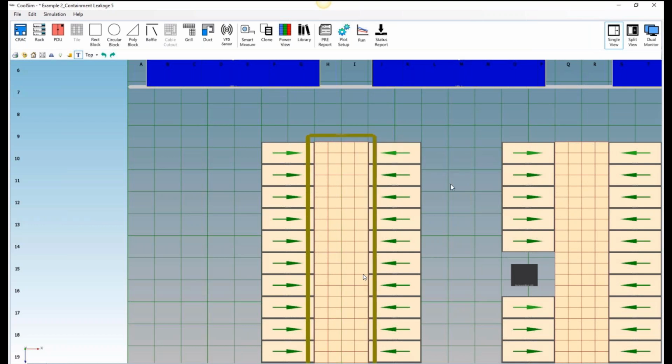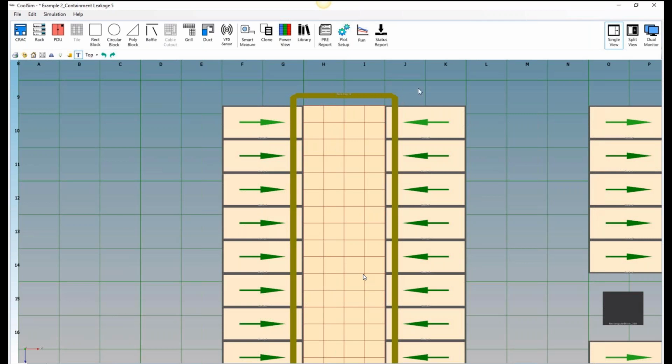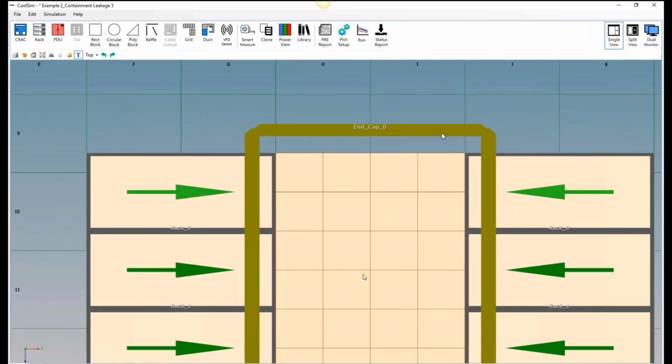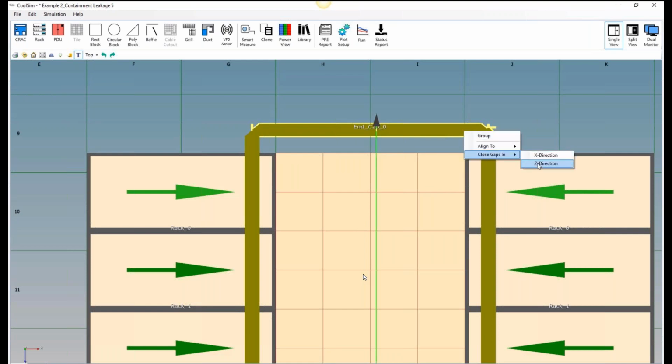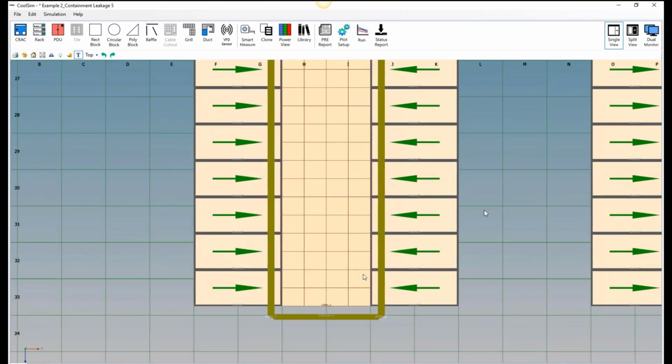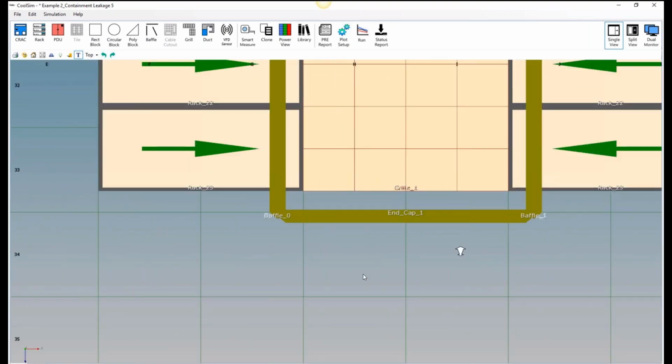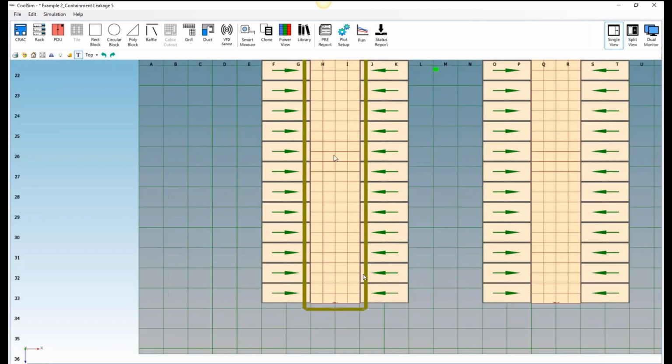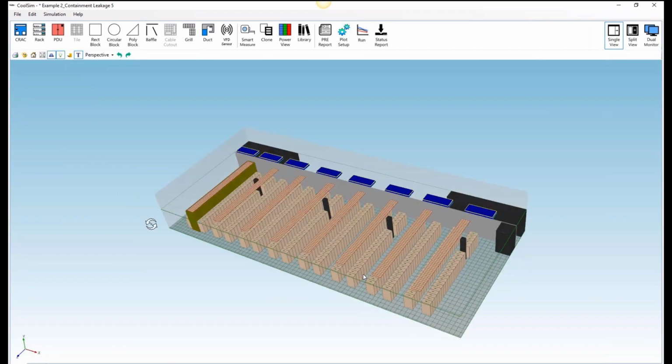So here I'm just going to set this back up. I'm closing the gaps, aligning the fronts, and looks like I still have a little bit there. I want that edge to be very clean, so I close gaps. There we go. And over here too, I put my cursor over the one I want to hold constant, and the other one moves accordingly. So I just check it. Yep, it's good at the top, it's good at the bottom. Those look good. I've got the side rails leaking at 5%.